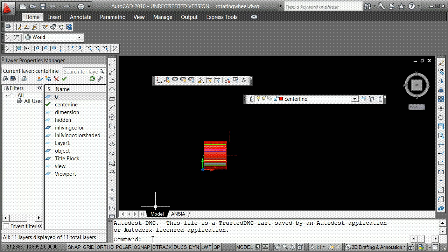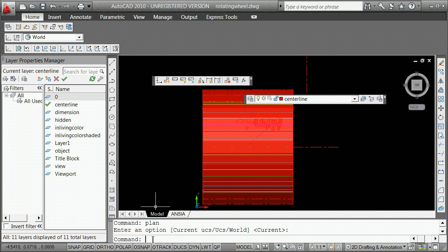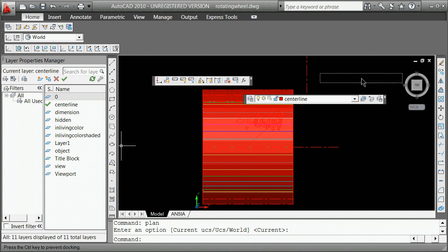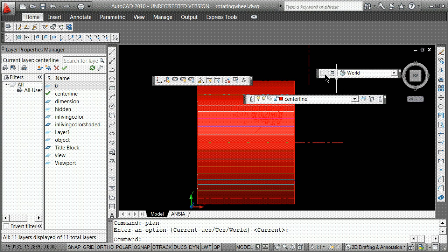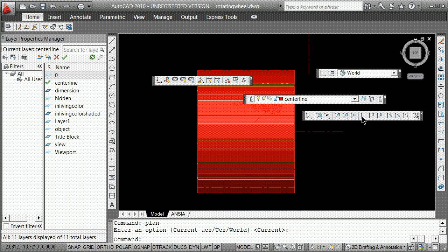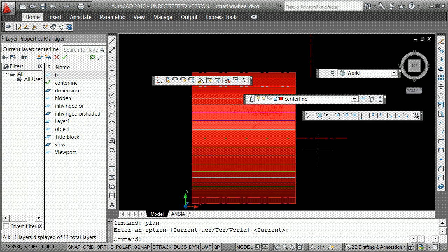And we want to see that there are different ways to go to the plan view, but that's a great one to always be able to hit because it puts you in looking straight down on a coordinate system. Now, the coordinate system I'm in can be kept track of right here in the toolbar, which is the UCS2 toolbar. That, of course, would be followed along with the UCS1 toolbar. So I'll put those out here, though I may be speaking a lot of these commands as well.